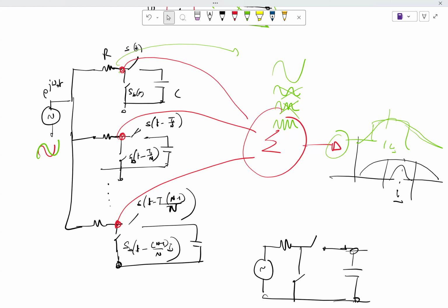So this only does that job. It does not say that if there is an input at 2 omega_s, it is going to get filtered. That's an important distinction to make, because at that time you will have to see the harmonic response of H of 2 omega_s. Right now, we are only doing it with H of omega_s.